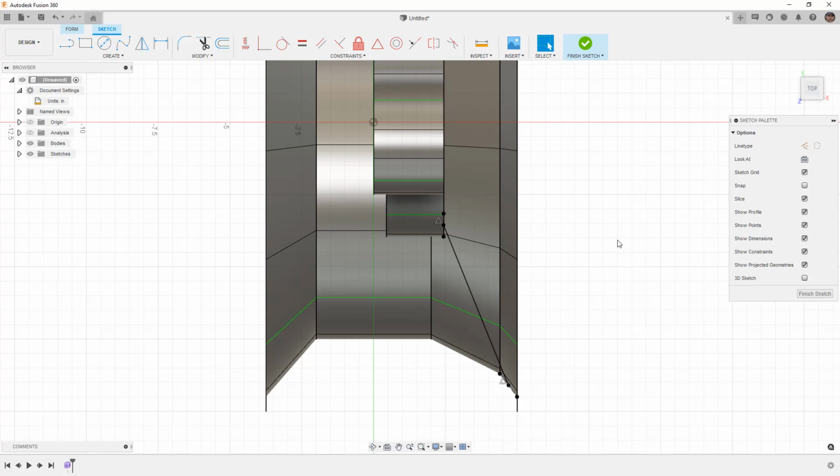For me, for the number of years that I've been doing this, when I am training, I try to avoid shortcut keys, which means I've gotten used to just going to the location where all the tools are. But in a professional sense, when I was designing products for customers, the efficiency of using just the S key, so that the mouse doesn't have to go all the way up to the toolbar, is a much quicker workflow, because that S key will bring up that shortcut wherever you are. So just a quick tip there.